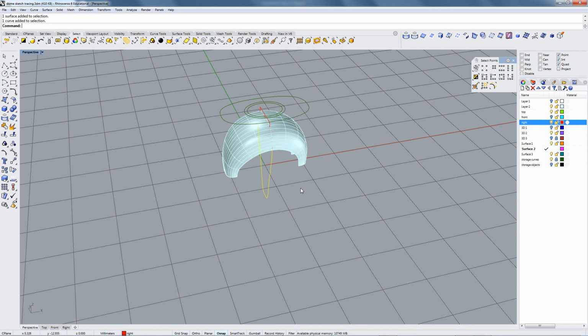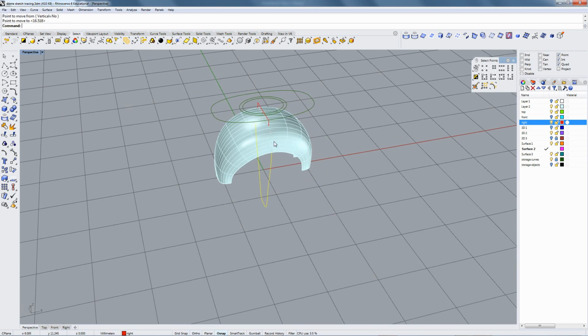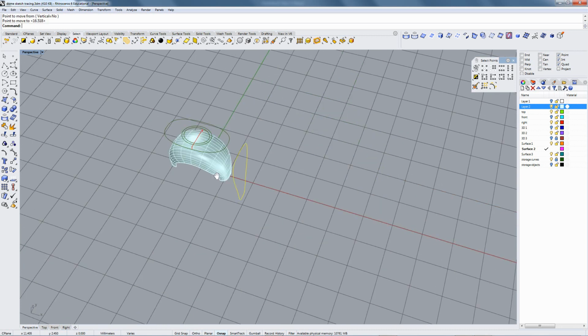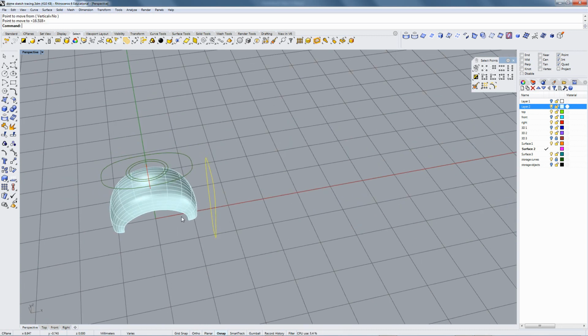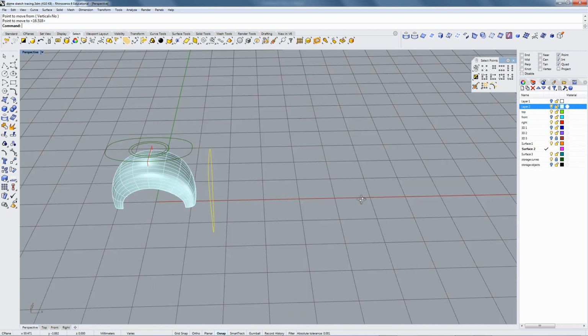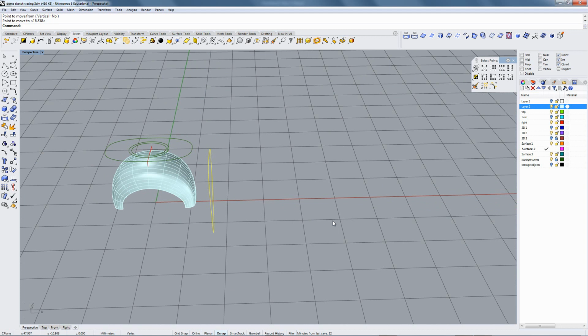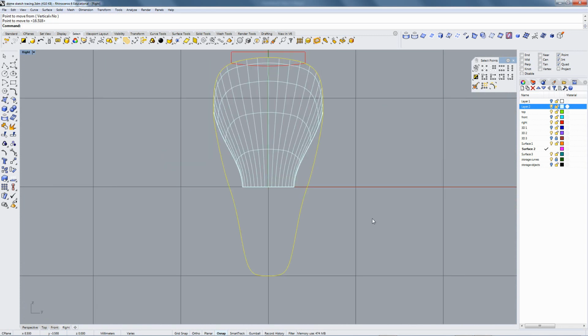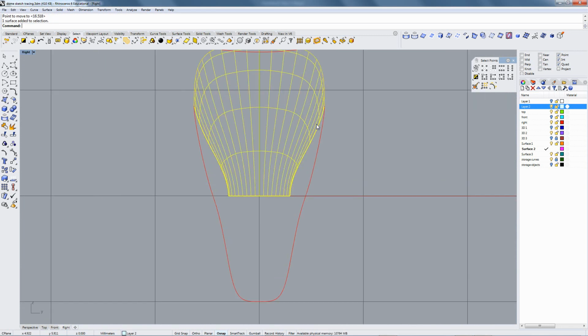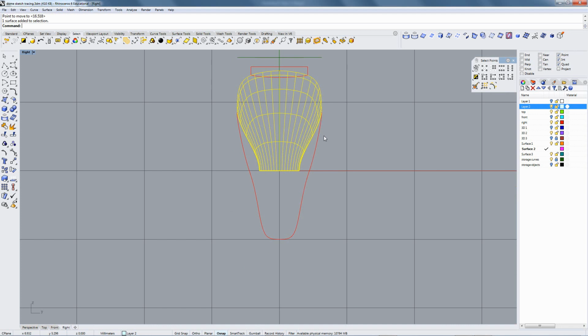I am going to move this view. Actually, I need all of it. Both pieces, and I'm going to move it off to the right. Now, by the way, in Rhino, the way you can tell you're off to the right is when you're looking down, your X axis line should go off to the right, and everything over here is on the right side. So now when I come into the right view, I should be able to modify this. I'm going to make a copy of this.